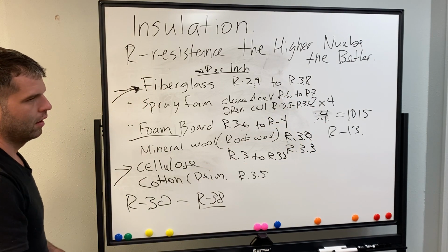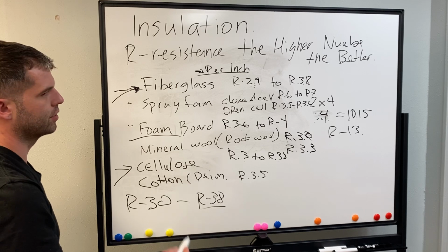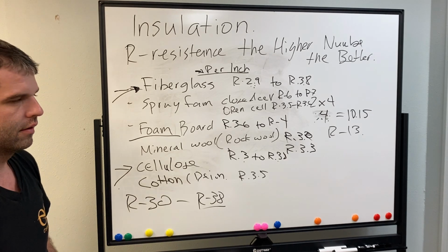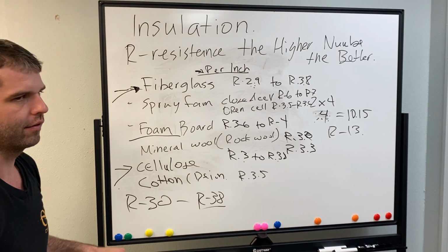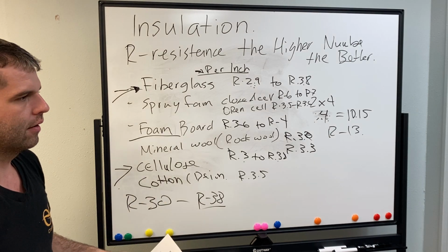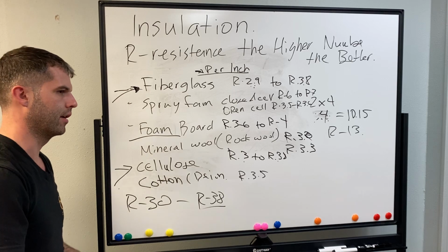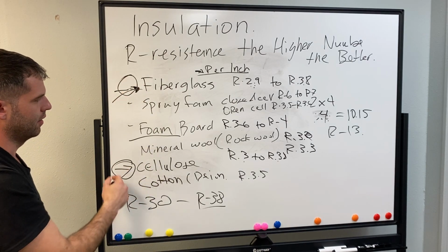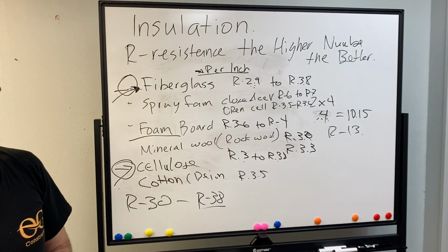And can we use the spray foam? You could use the spray foam, but it's not really commonly practiced, because you need a lot of different kinds of equipment to actually spray it in. So the most common one you're going to see is fiberglass, or cellulose. If it's freezing temperatures, you can't spray foam.